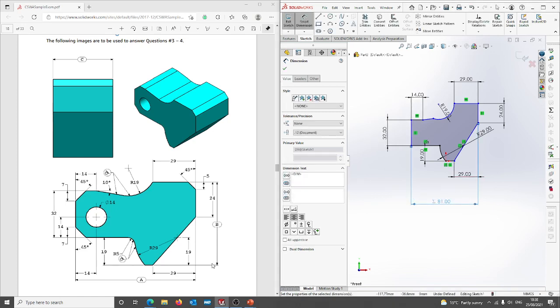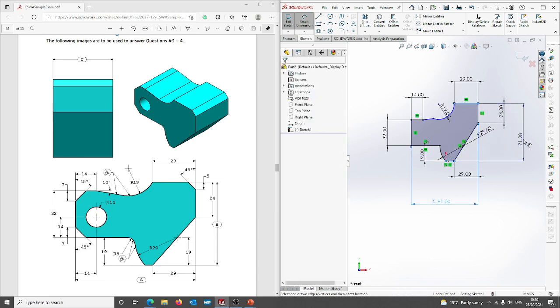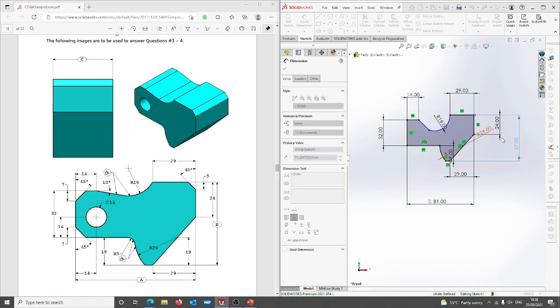And then we know that this bottom to this top is equal to the global variable B, so again we'll do that as well. Just type in equals, quotes, capital B, quotes, enter, and that is making that equal to here.